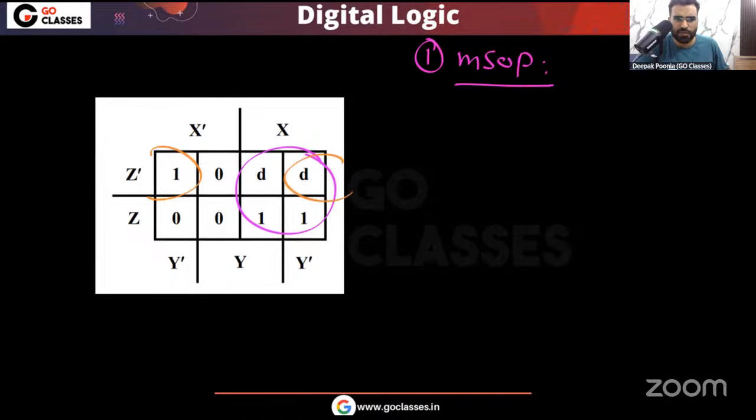That's it. We have covered all the one cells with cubes as large as possible and the minimum number of cubes. So now let's see what will be the product term corresponding to this pink cube. This pink cube is in the area X. You can see this is in the area X. So for this pink cube, the product term is basically X.